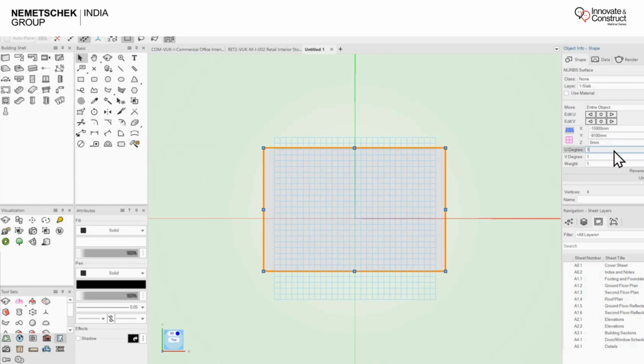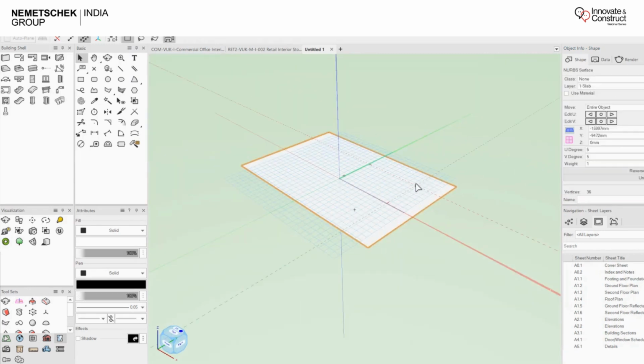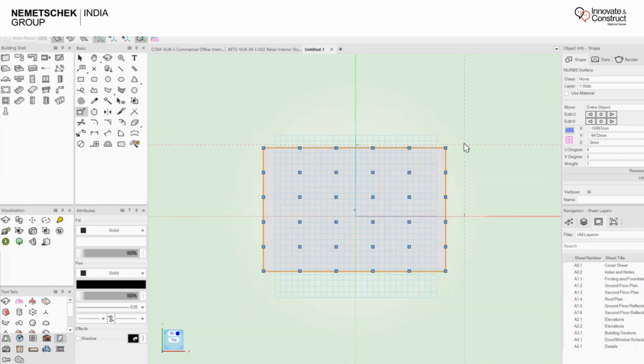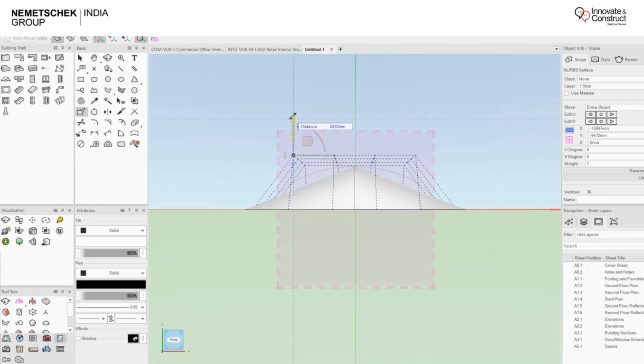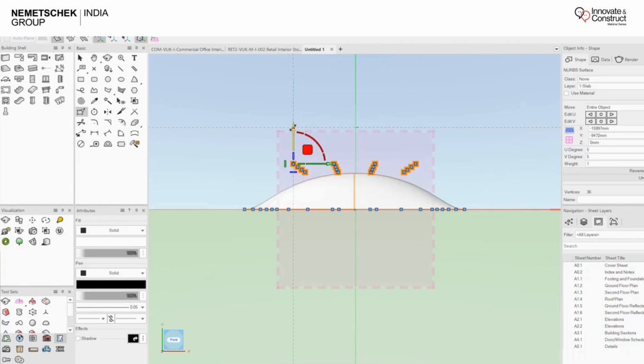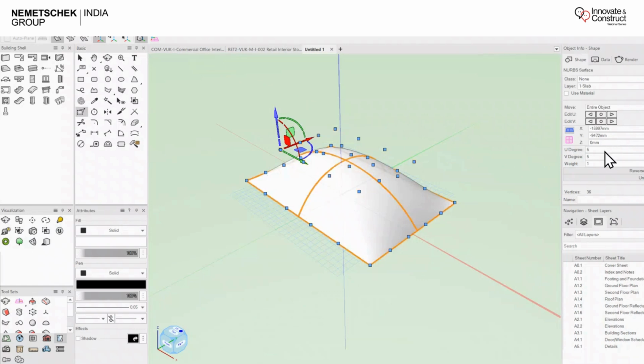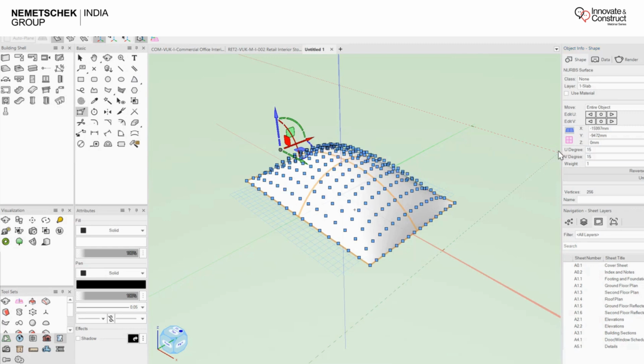and once it converts back to a curve, it has a u degree and v degree, which can be further customized. So say phi and enter. So I can always see, and if I see this, it further gives me points where I can customize or leverage this as well. If I do something like this where I can squeeze it, it will give me the curve profile as well, as much as you want. If you take it to 15, you can also further customize this however you want. So you can really carve out whatever you want.